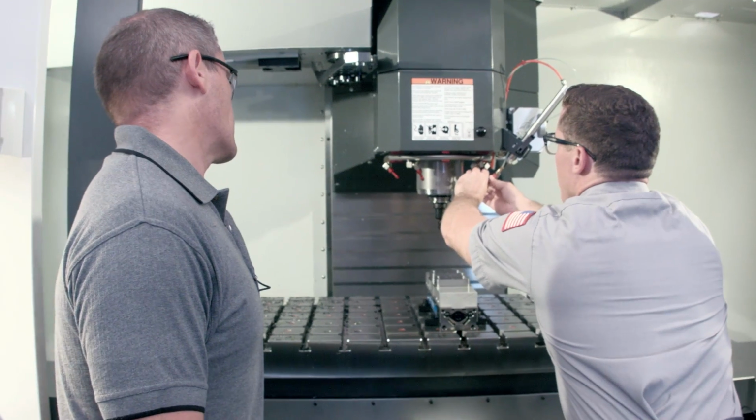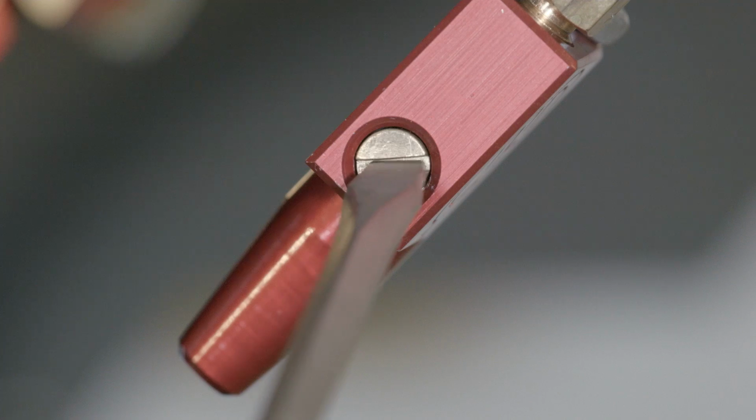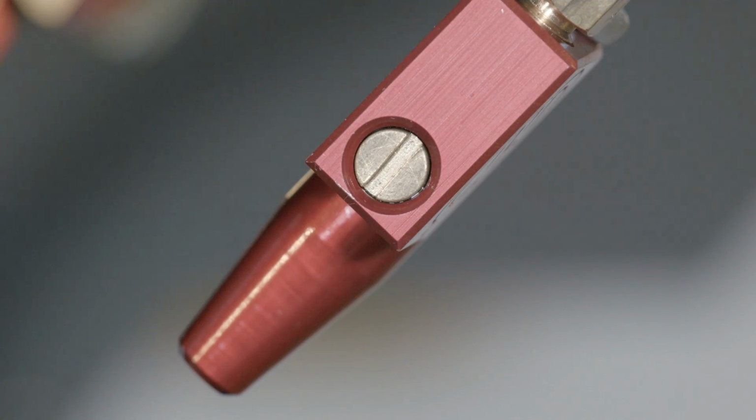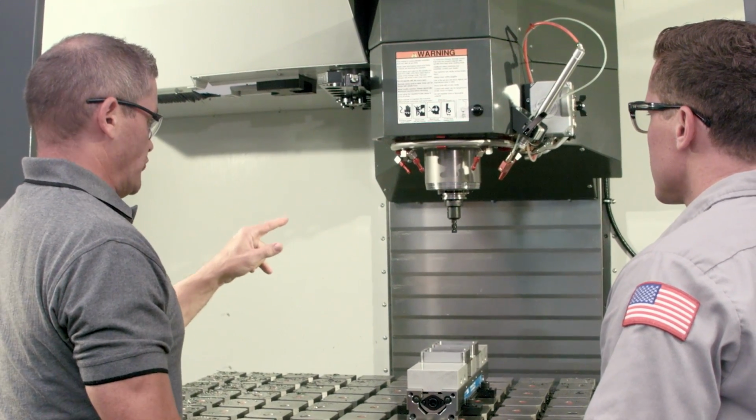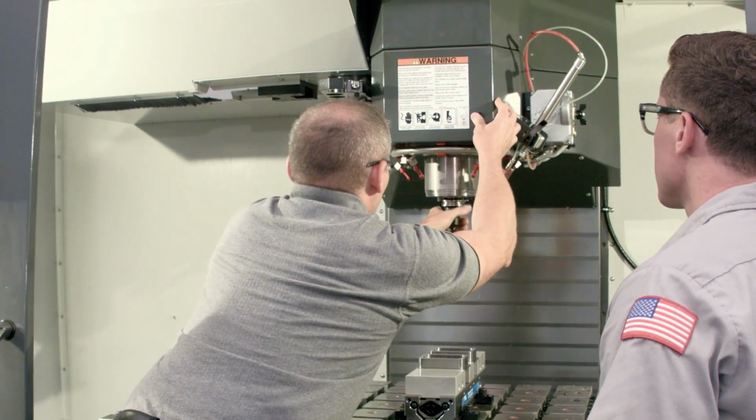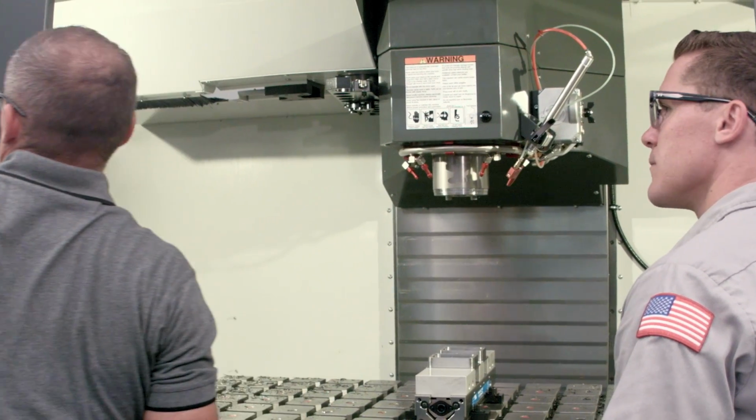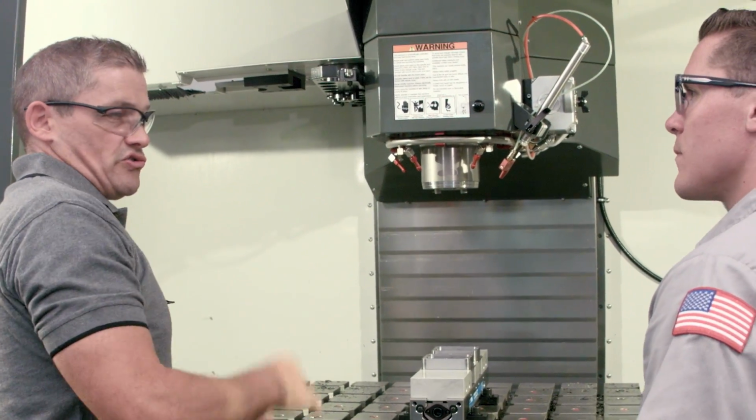From here, adjust the atomizer screw to about 1/4 of a turn out. This is a good initial setting. Remember, if you can see oil mist coming out of the nozzle, you probably have it set way too high. So you've got your atomizer set. Now, I'm going to take this tool out of here, and then maybe you can show us what happens as you increase your atomizer setting.